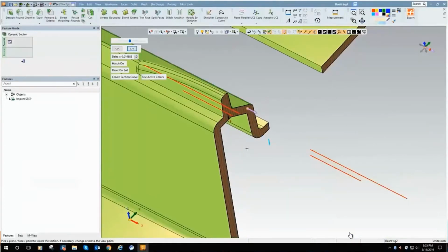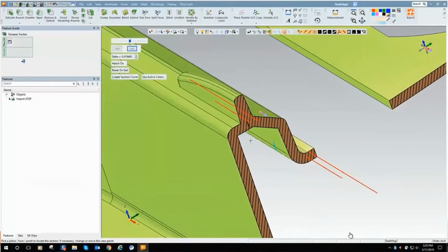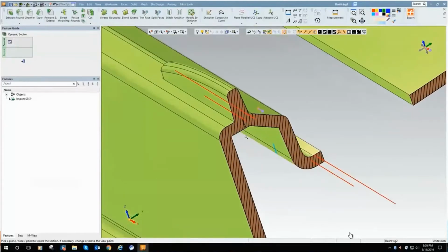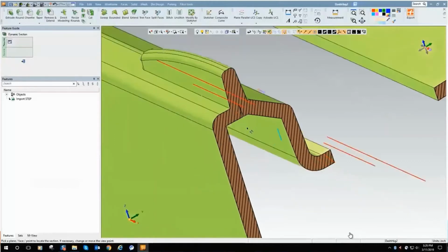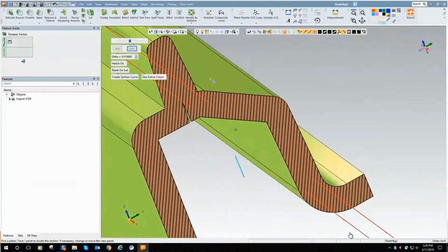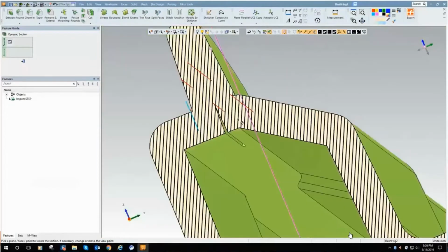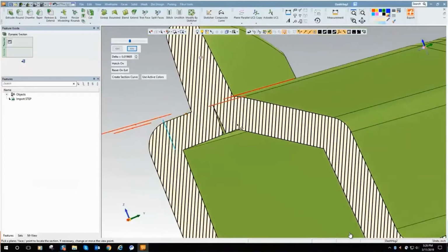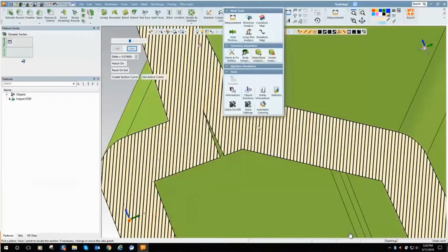And then the last condition the analysis looked for was called knife edges. This was also a variable. We had to check for part angles that were under 10 degrees. What it found in red can best be seen by sectioning the part. Good plastic part design avoids very narrow areas because they would require blade-like steel in the mold. So often, you may find that a discovered knife edge is really a small mistake in the wall thickness offset or from features that do not completely touch. Either case is basically a design error that should be examined and corrected.